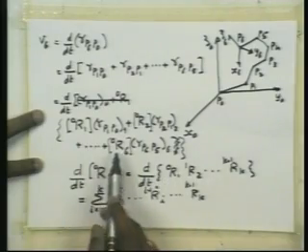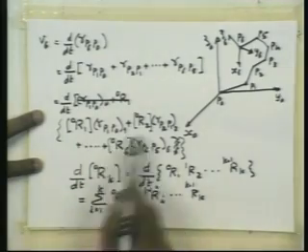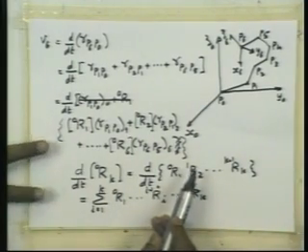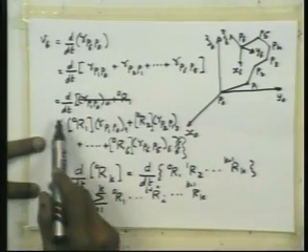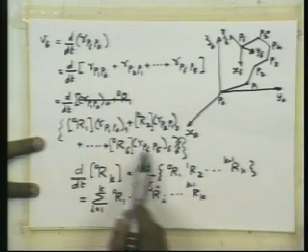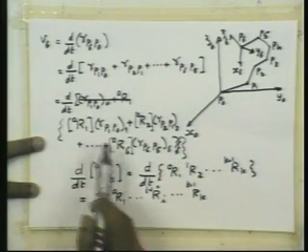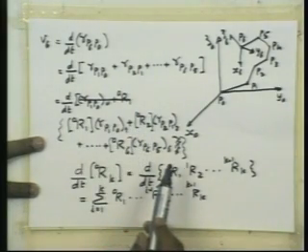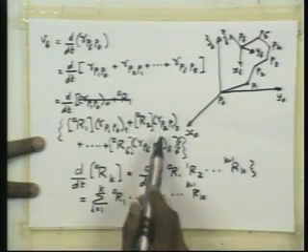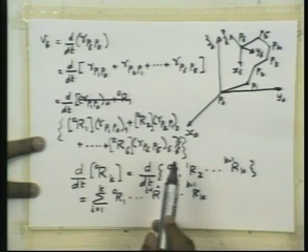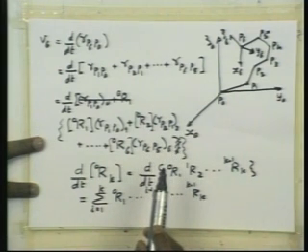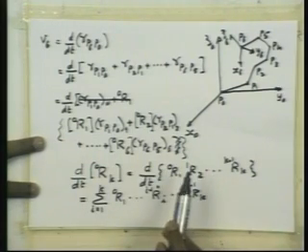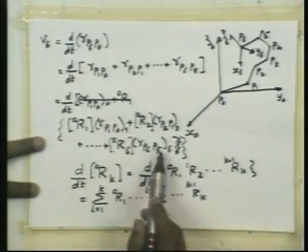Right? So that is how each of these vectors can be expressed. So now when we take the derivative of this particular expression, we need to take the derivative of each of these rotation matrices. These vectors are now expressed in the local reference frame, and so they are fixed quantities, so they don't have a time derivative. So the time derivative is 0. So we don't have to take separately the time derivative of these vectors.